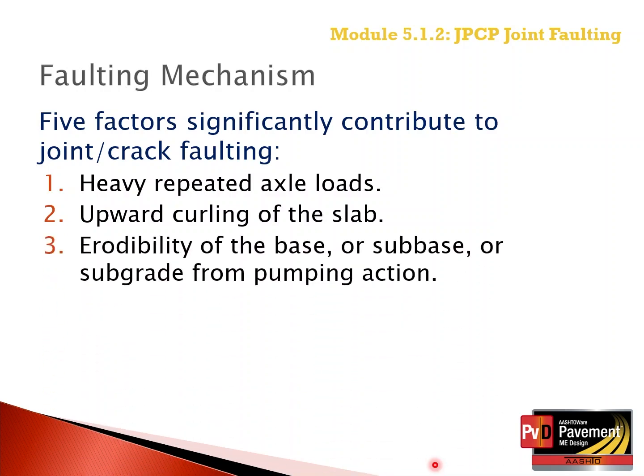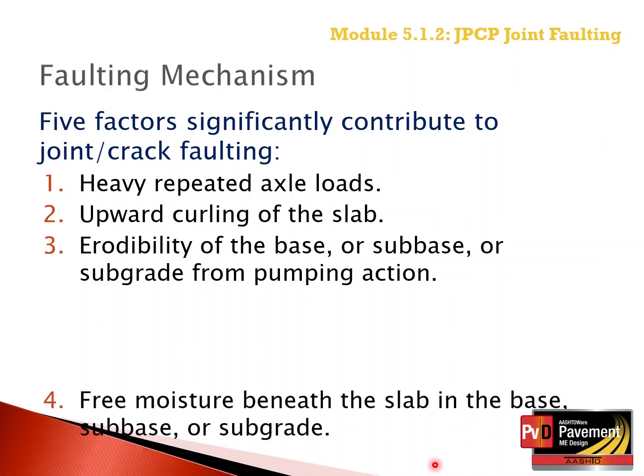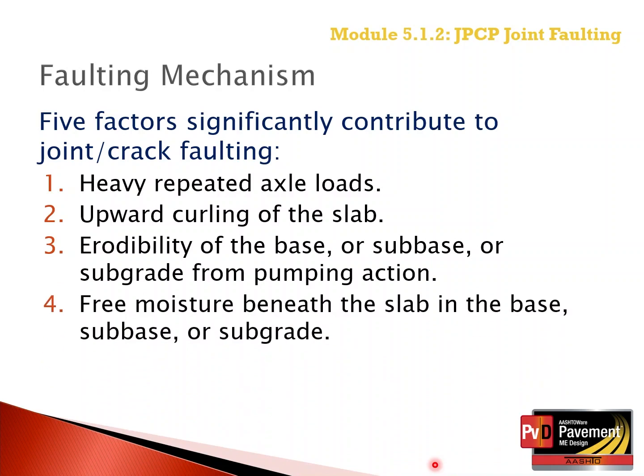The third is the erodibility of the underlying base or subbase layer and subgrade from pumping of fines. The fourth, which is tied to the third, is free water beneath the slab in the base, subbase, and or subgrade layers.